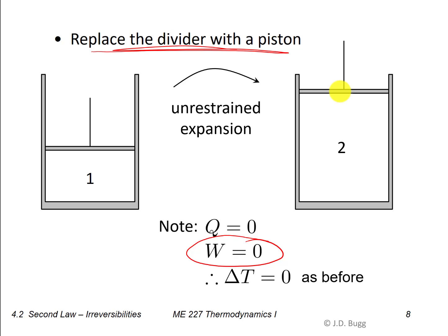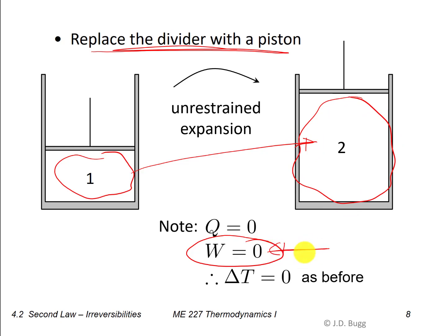Realize here we're talking about the work done by this gas. And we're asking ourselves, as it goes from there to there, is this gas doing work on its surroundings? Well, we've concluded here that it isn't, that the work is 0, but I want to talk about that a little bit more. Remember when we were doing work calculations for closed systems, and that's exactly what this is, we were calculating work as the integral of P dV.